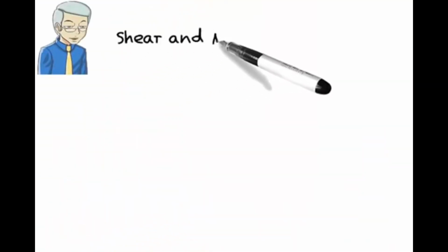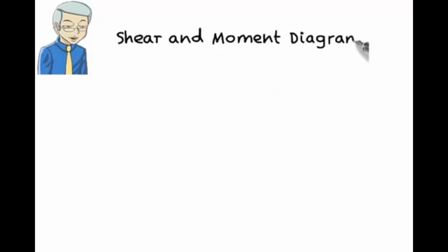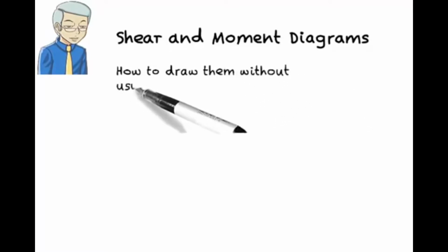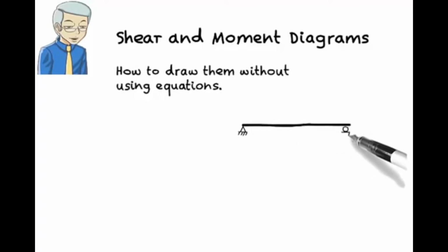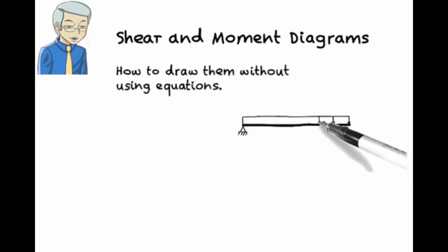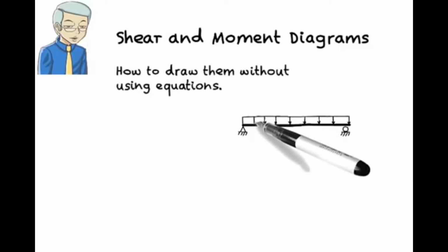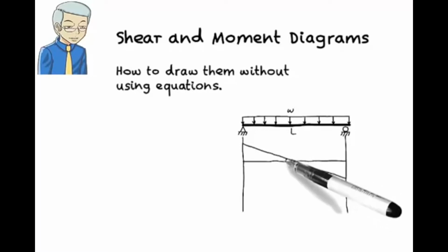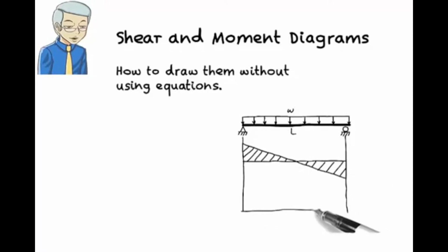and moment diagrams. In this lecture we focus on drawing shear and moment diagrams without the use of any equations. This is particularly useful for practical structural analysis and design. More specifically, we're going to learn how to construct the shear diagram directly from the load diagram, and how to construct the moment diagram from the shear diagram.